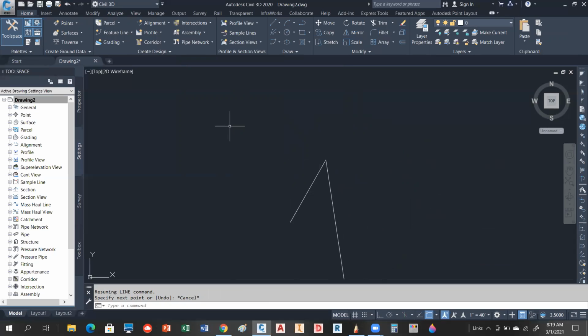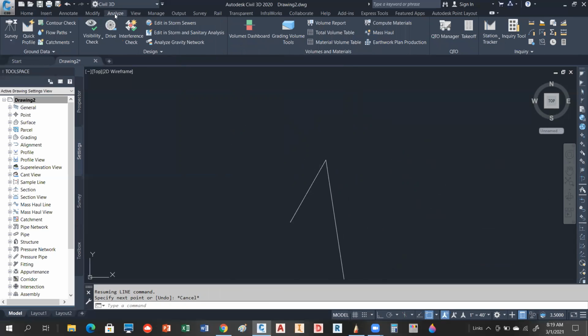And again, another really cool tool, if we go to the Analyze tab, over here they have this one called angle. So you just click on the two lines, and it spits out the acute and the obtuse angle between those two. So you can see what I've got on there, 38, 52, 40. Okay, so if I'm looking at something or I think something could be wrong, that's a good way of looking at it. All right, everybody getting those to work?